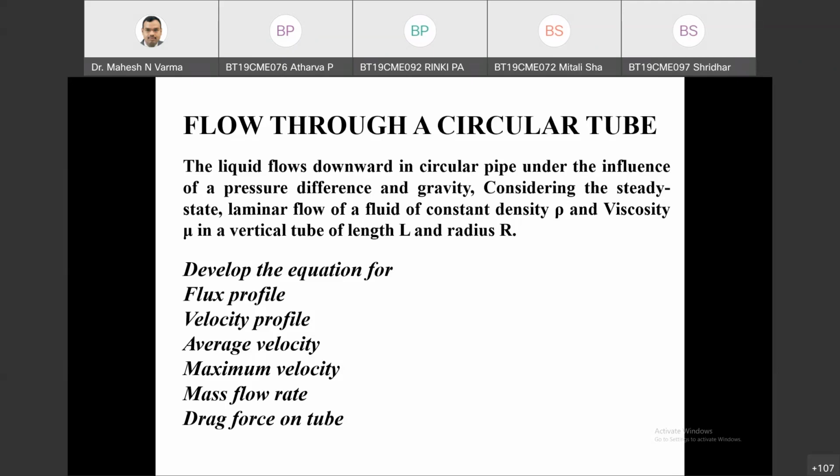Okay. So which velocities do you have now? Vr, V theta, Vz. So which are zero and which are non-zero? Sir, there won't be any velocity in the radial direction, so Vr will be 0. Very good. And we'll have some velocity in the z direction because it's falling downward. That leaves V theta, which will be 0, sir.